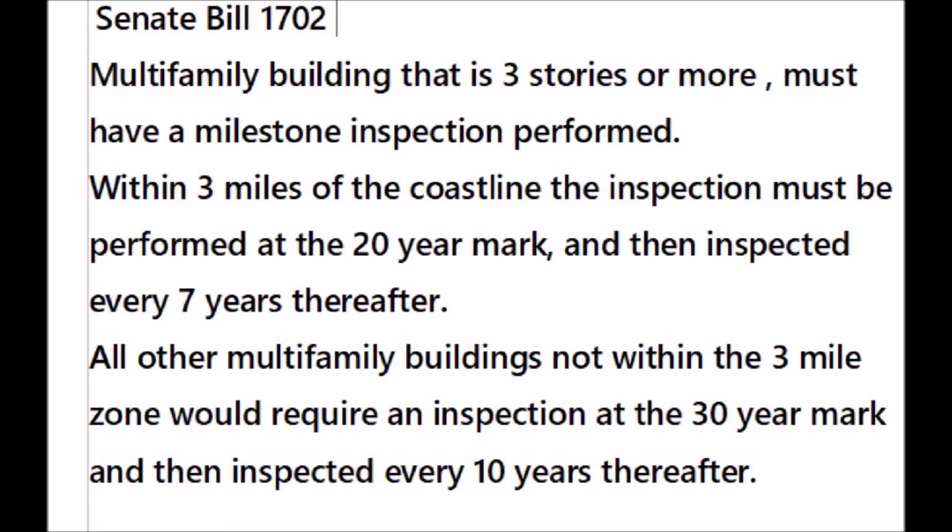We know that in response to this collapse, the Florida legislature has passed Senate Bill 1702, which now states that every multifamily building that is 3 stories or more must have a milestone inspection performed. Within 3 miles of the coastline, the inspection must be performed at the 20-year mark and then inspected every 7 years thereafter. All other multifamily buildings not within this 3-mile zone would require an inspection at the 30-year mark and then inspected every 10 years thereafter.